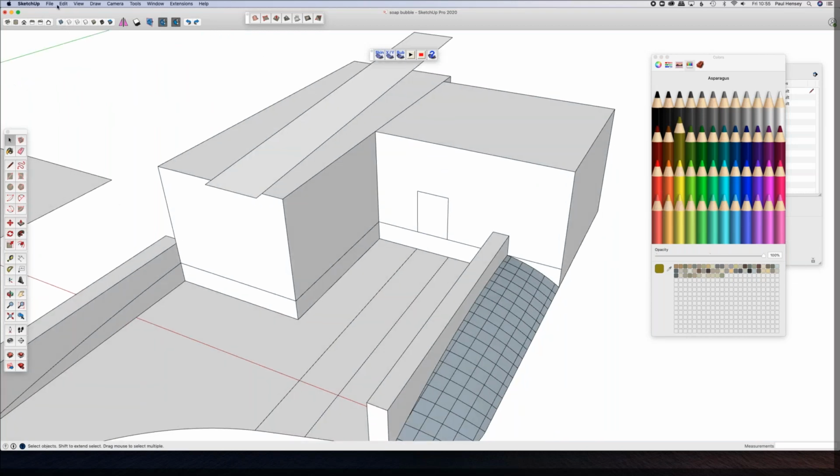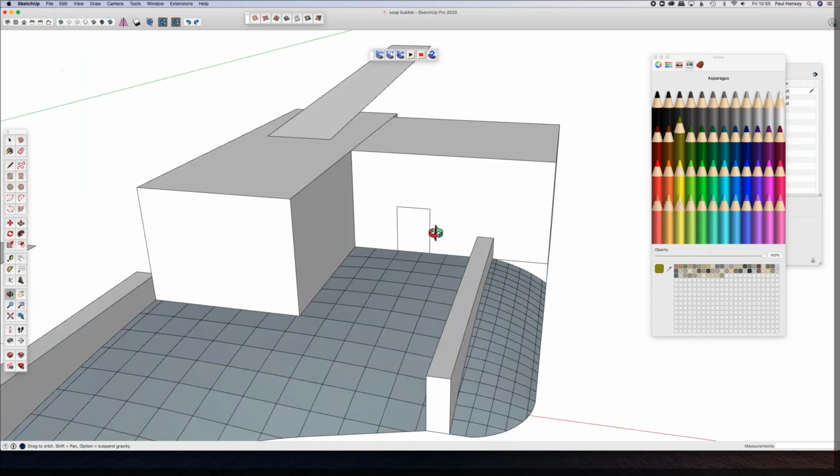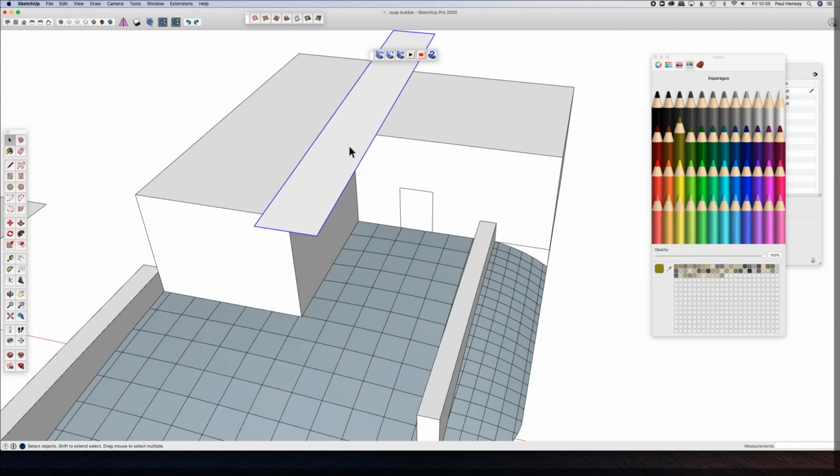And then I'm going to unhide my piece of terrain, and I'm going to drape this into this. So I'm going to pick this geometry and then drape. Do I want it to have an offset? So maybe I'm going to pick something like 0.1. What does that look like? Maybe something like 0.2. So we'll see what that does.